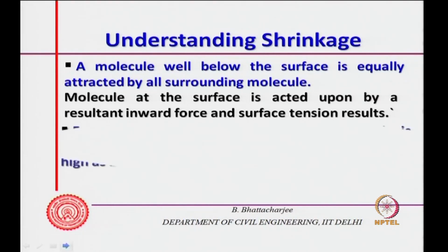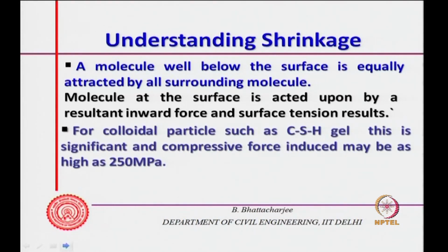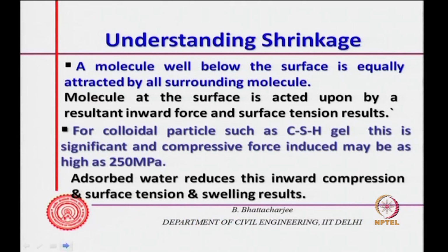And for colloidal particles such as CSH gel, this is significant, for the CSH system also this is significant, and the compressive force induced could be as high as 250 MPa. So, if it is dry, there is a compressive force acting downward into the skeleton, and this could be as high as 250 MPa. Now, I bring in adsorbed water, which reduces this inward compression and surface tension, and swelling results.